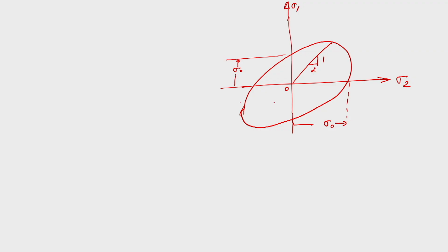In elastic deformation region, whatever is inside this ellipse is the elastic deformation region. Stress and strains are directly related and can be calculated very easily, because it follows Hooke's law and other things. So, it is very easy, you get direct relationships. But when you come to plastic deformation region, there is no such relation which exists, and it may happen that at some stage material may be under the state of stress, but there is no change in the shape.